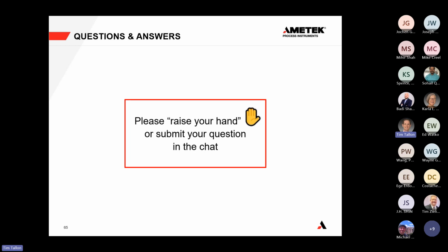Now, for fired heaters and refineries, we've seen that value to be approximately 1,500 parts per million of combustibles. But that's really where there's, if not a shutdown, there is at least a much stronger investigation on what's going on to ensure that the analyzers, to ensure that the firebox is diagnosed correctly.